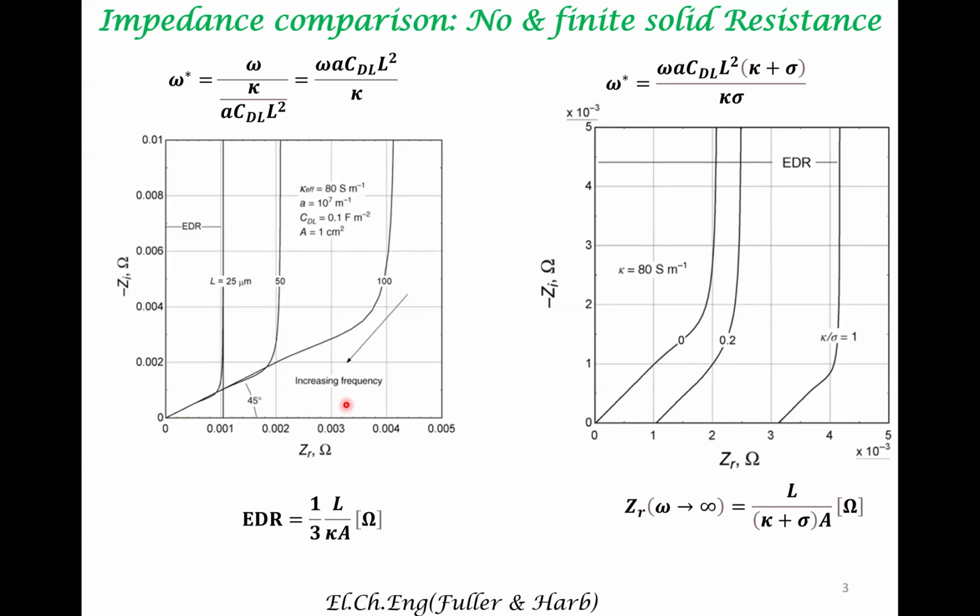We also interpreted that as the capacitor not being utilized. Only the front part of the capacitor facing the electrolyte feels the potential drop, and the potential drop does not percolate across inside the porous electrode. Therefore, there's no current inside the porous electrode.